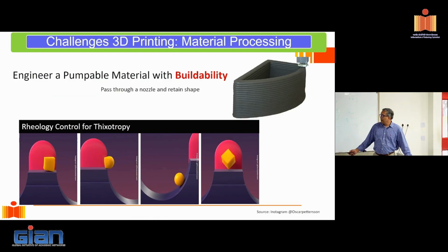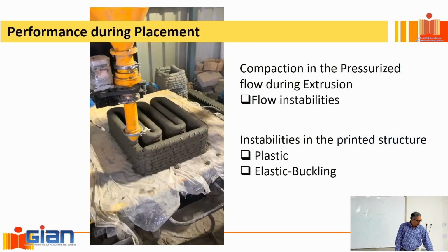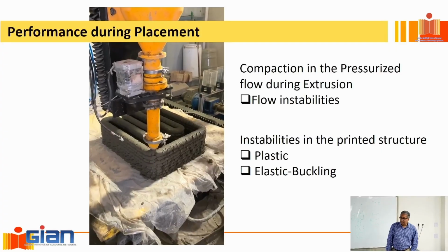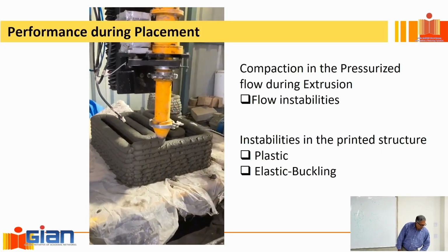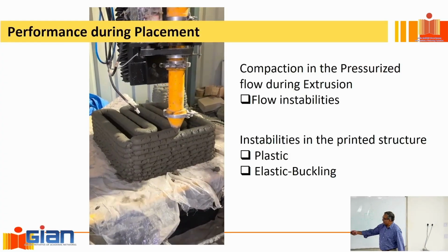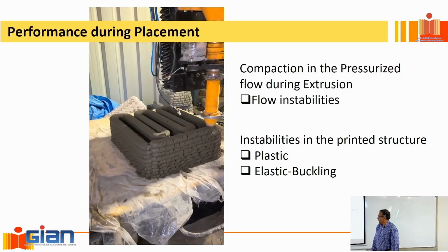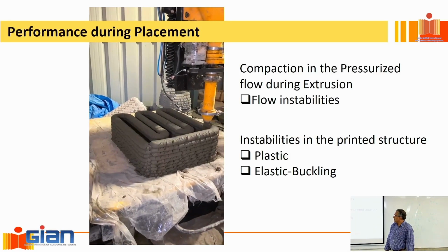And this whole thixotropy then comes into play with buildability, right? I've already illustrated this to you. I'll skip. So this is the other thing: you get this instability when you're printing. Some of you are printing and probably notice this, that everything is going well up to a certain point.